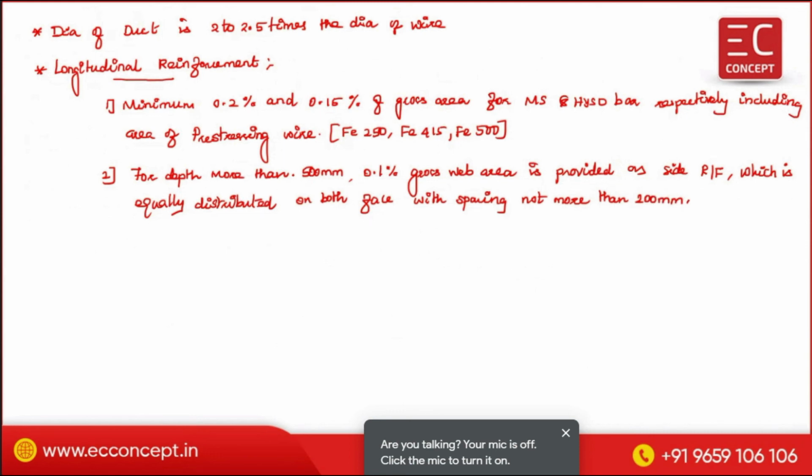For depth more than 500 mm, 0.1 percentage of gross web area is provided as a side reinforcement.